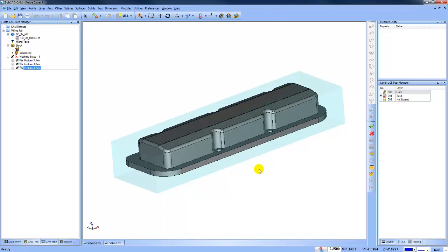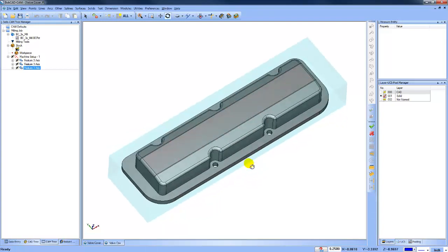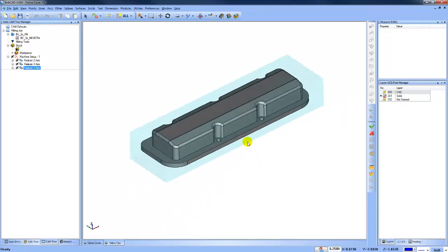What is the best way to do an open pocket when all you need to do is go all around? If you don't need to go all the way around the part, you can do a 3-sided open pocket. You could do a 2-sided open pocket or a 1-sided open pocket. So that might work for you. Or in 3D with advanced roughing, you can use operation stock in order to limit where toolpath is going. So that's the Q&A from stage 1.